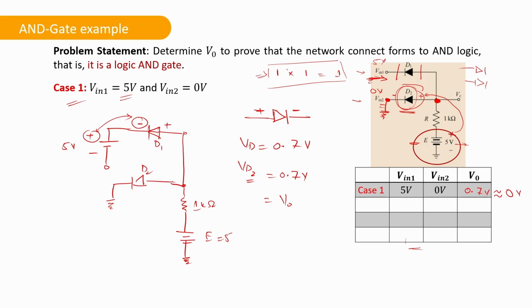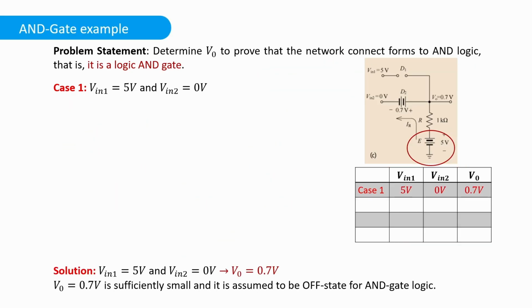Now let's go and see the second logic or second case where we will have an input at the second terminal over here and no input at this terminal. We are doing the second case. Actually, this case is same as the previous one, which we have already done. So just to show you the figure over here, when we applied 5-volt input over here, and this was grounded, we saw that this is open circuit. And this is open circuit because diode was on reverse bias condition.